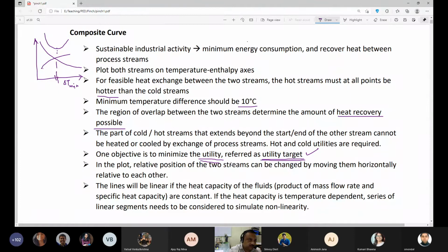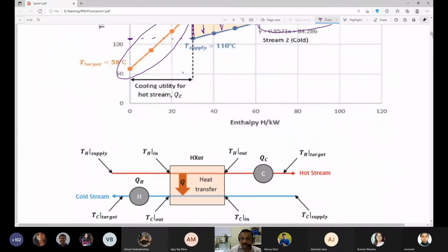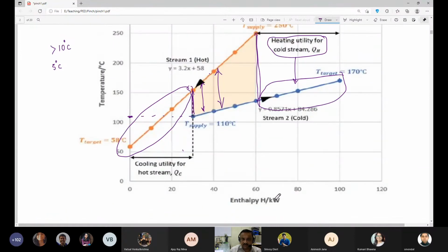So now you can find out what would be the annual expenditure as far as acquisition of that capital equipment is concerned. So you can annualize that cost. And similarly, operating cost: how much steam is condensing. We talked about enthalpy in megawatt, but here we have enthalpy in kilowatt. So this much enthalpy, delta H, is to be provided by the steam.